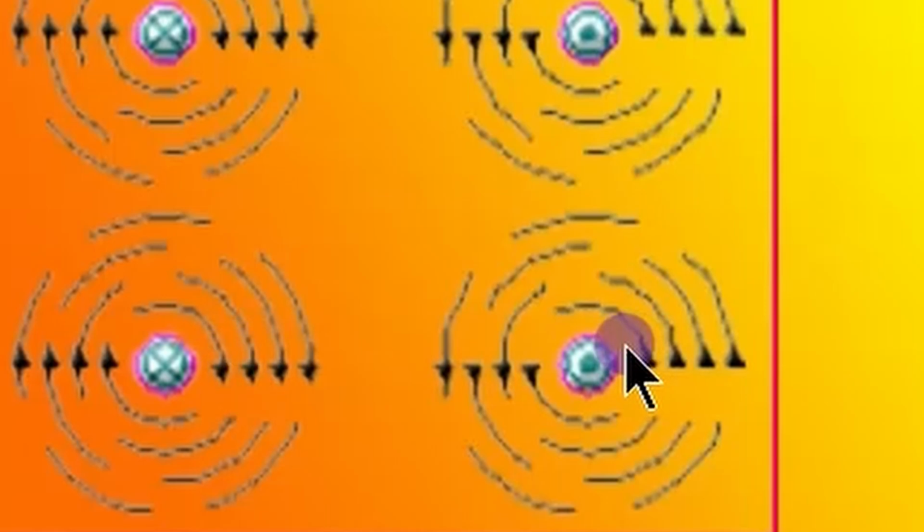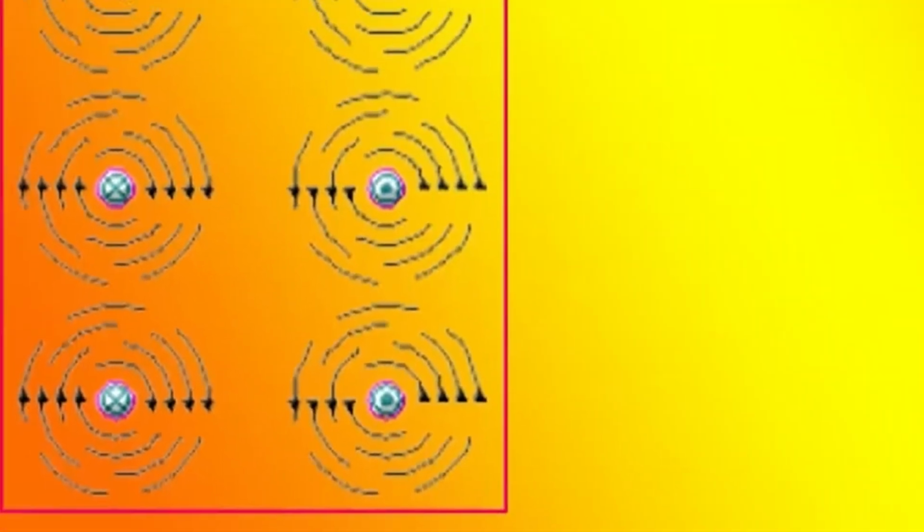And when current is coming towards us in this conductor, see that dot, that is, the current is coming towards us, the magnetic field is in anti-clockwise direction. See, in all these conductors going away, so that the magnetic field is in clockwise direction, while here current is coming towards us, so in all these conductors it is in anti-clockwise direction.